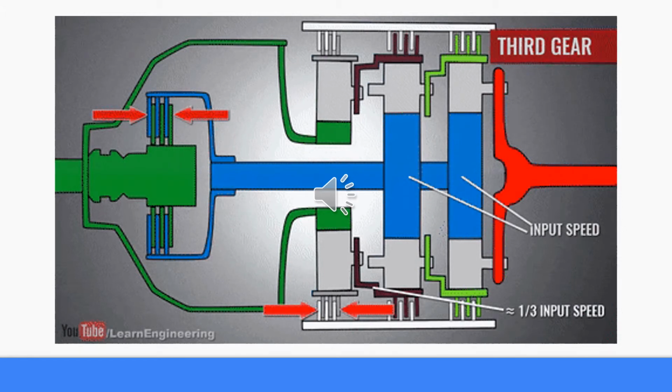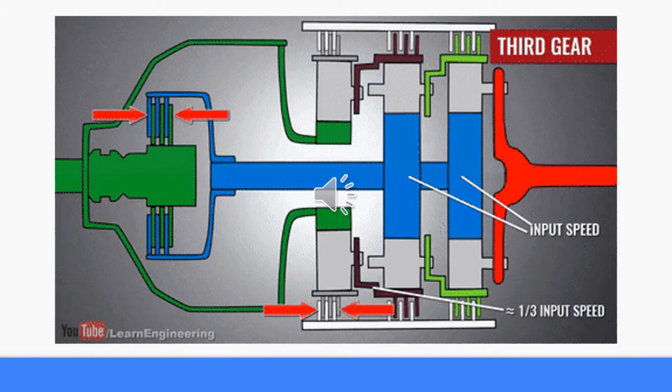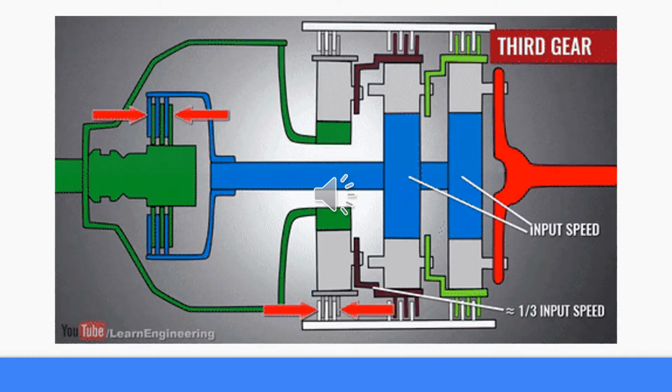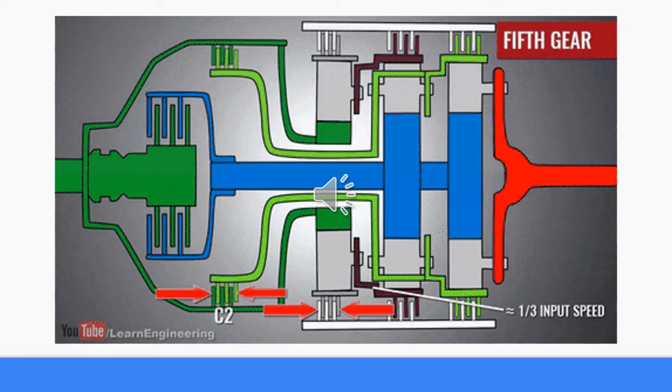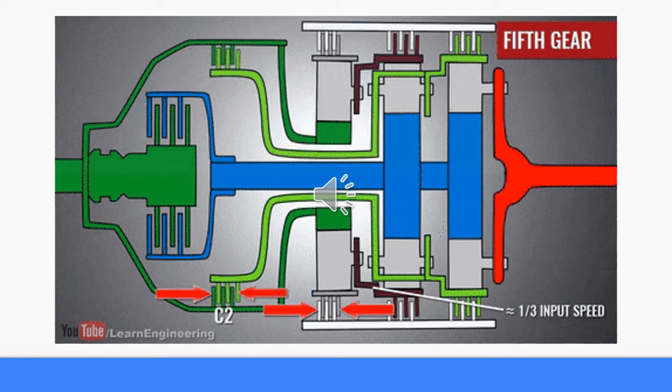Automatic transmission uses a system of epicyclic gear trains. To effect gear changes, one of two types of clutches or bands are used to hold a particular member of the planetary gear set motionless while allowing another member to rotate, thereby transmitting torque and producing gear reductions at the same time. Engagement and disengagement of clutches is either hydraulically controlled or electronically controlled. Cars with automatic transmission lack a clutch pedal.